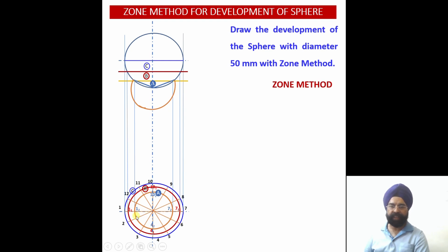So whatever is the width for the first sector, same will be the width for the remainder of the sectors over there. So what I am going to do, please see, I will be making this distance. I am going to measure this distance, and once I measure this distance corresponding to one sector, I am going to draw starting from here 12 arcs. Arc number 1, arc number 2, arc number 3, arc number 4, so on till I reach 12 and then get back to 1. So 1, 2, 3, 4, 5, 6, 7, 8, 9, 10, 11, 12 and then 1.